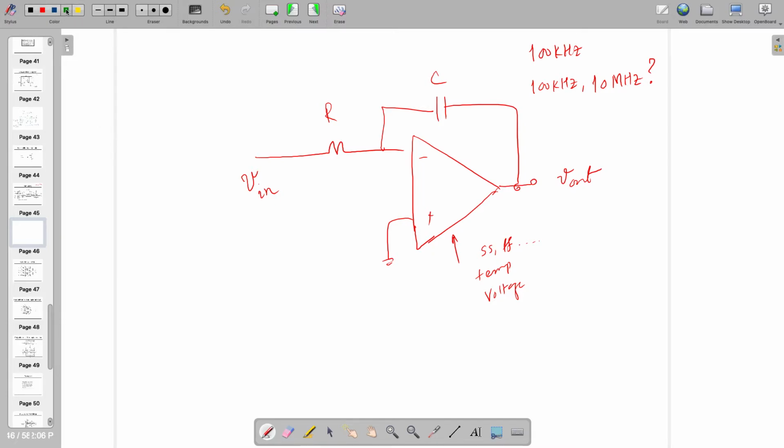We can make these resistances or capacitors tunable. Look, one of the things which is tunable is going to give me this equation, 1 by 2 pi RC. Let's say, instead of changing the value of C, I am going to change the value of resistance. I can do that, right? So if I am doing this, then I can tune it for a given corner, or for any value I can do that. But the most important part is how to make this potentiometer. How to tune it? What do you think?